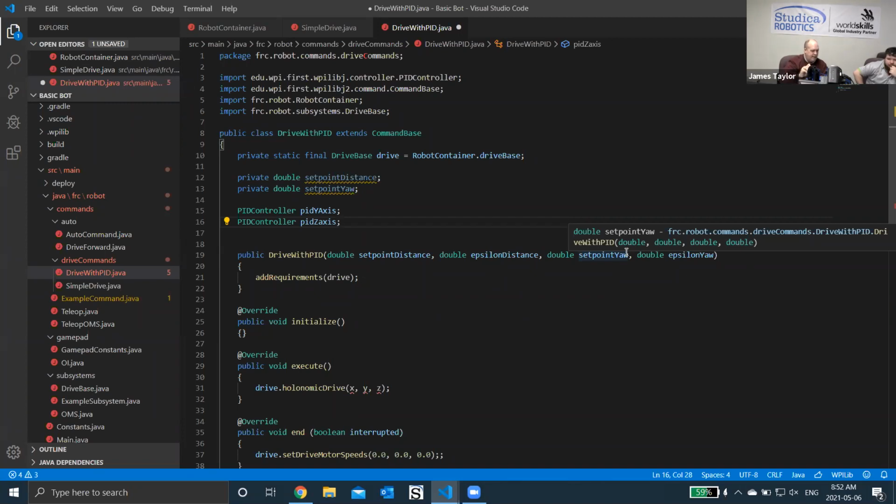You're going to have to reorient everything. That's why the default forward axis on the IMU is the Y axis, and why this is mounted flat in the top center of the robot. That's what gives it the forward motion, and then the Z axis, with the right hand rule, is up. So that's what we're using for the rotation.